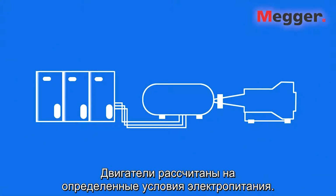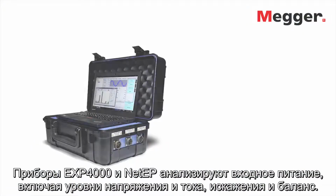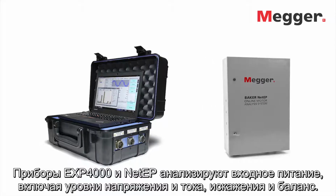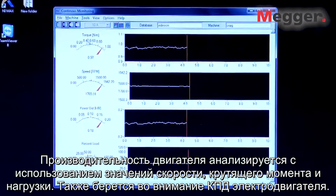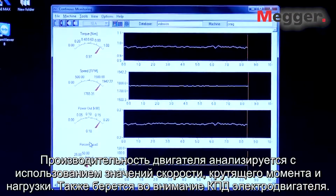Electric machines are designed for good incoming power conditions. When power conditions deteriorate, excessive currents can flow in the machine, generating excess heat and shortening machine lifetime. The EXP4000 and NET-EP analyze incoming power, including voltage and current levels, distortion, and balance. The motor performance itself is analyzed using motor speed, torque, and load ratings. Motor efficiency is also presented.